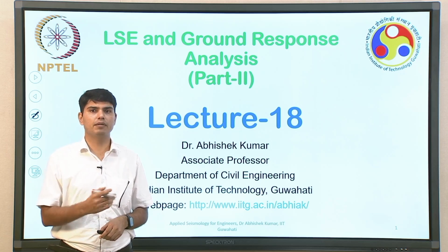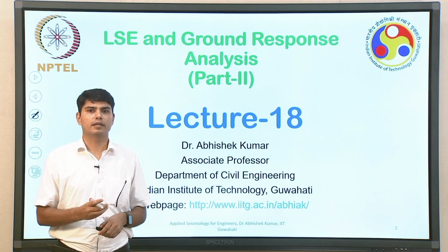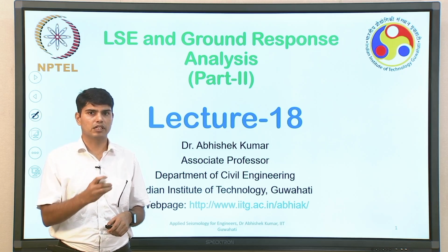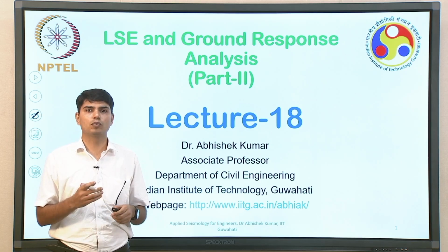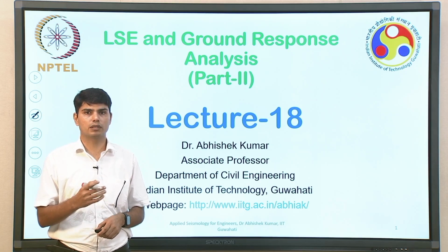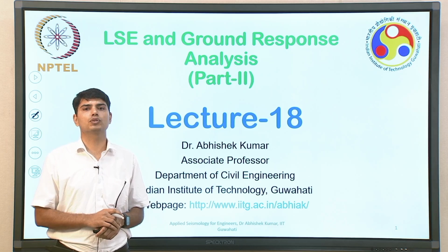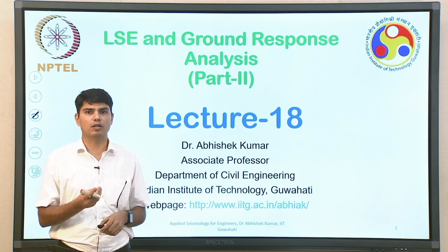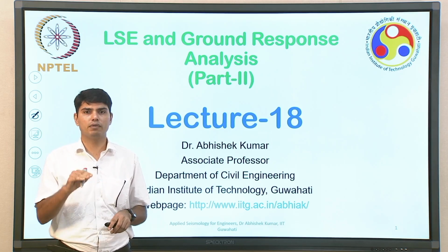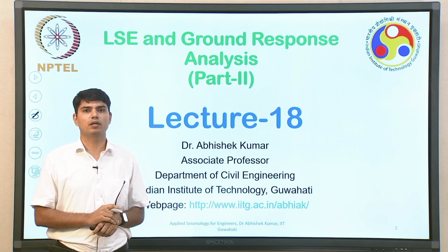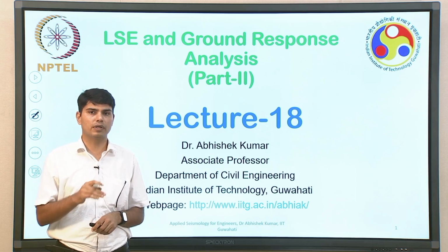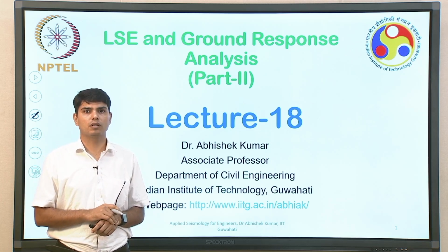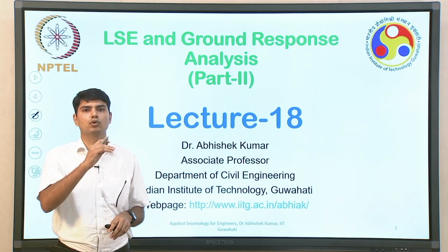In lecture 17, we also discussed that, equally with respect to soil characteristics, it is also important to know whether the ground motion which has been given to a particular analysis has been defined at bedrock level, that means the rock level which is beneath the soil layers, or as outcrop level, that means where the rock is exposed to the ground surface, or whether it is a bedrock outcrop motion where bedrock is there but there is no soil above it.